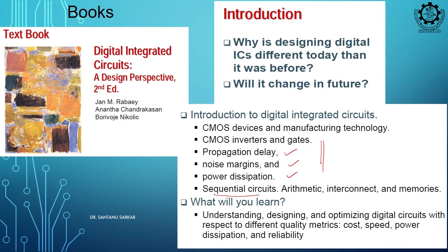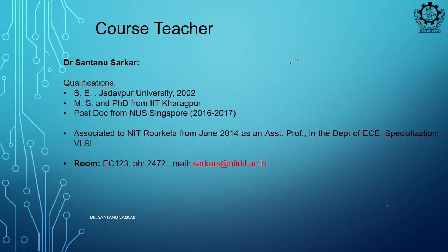How many logic design styles are you familiar with? Static and dynamic. So this is CMOS design, right. You are familiar with static CMOS design as well as dynamic CMOS design. There are other logic design styles also, like pass transistor logic and complementary pass transistor logic, CPL. We will be discussing those and which one is more efficient from a low power perspective. That we will check.